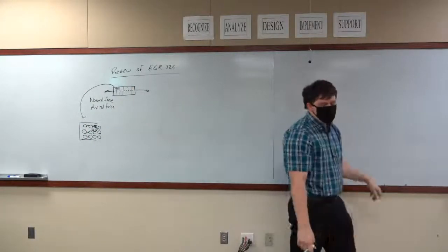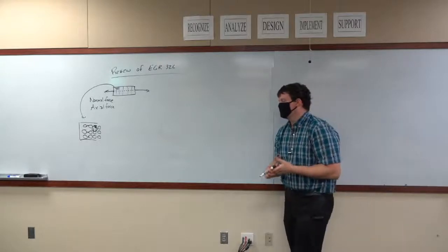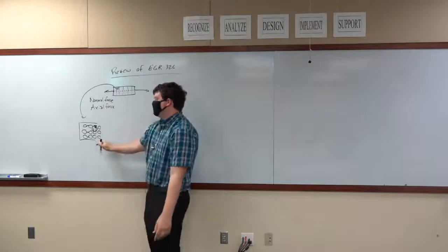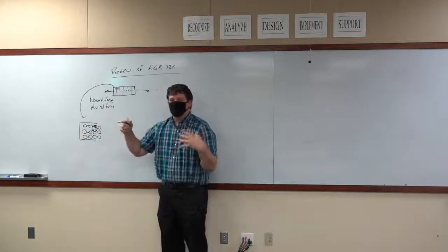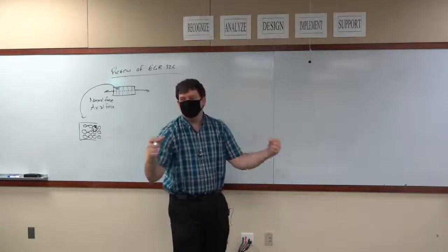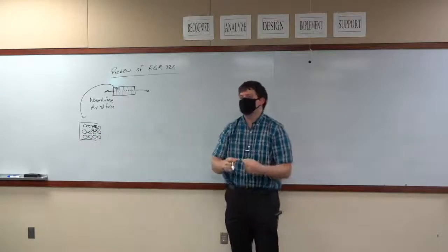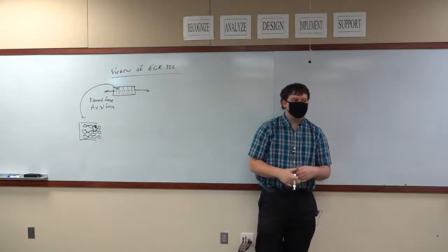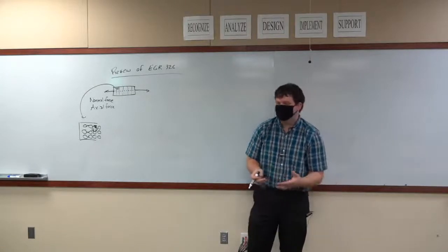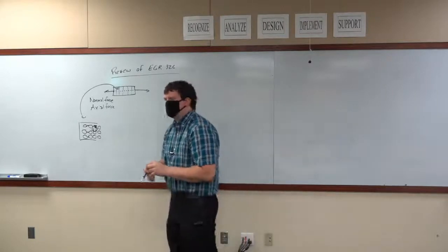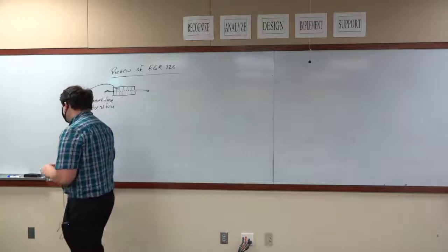When we come up with standards for materials, what we're looking at is we're actually looking to see what the typical crack sizes are for that material and how much you can pull on it before those cracks propagate all the way through the entire material. So standard 1020 steel has a fracture strength around 32 kips per square inch.